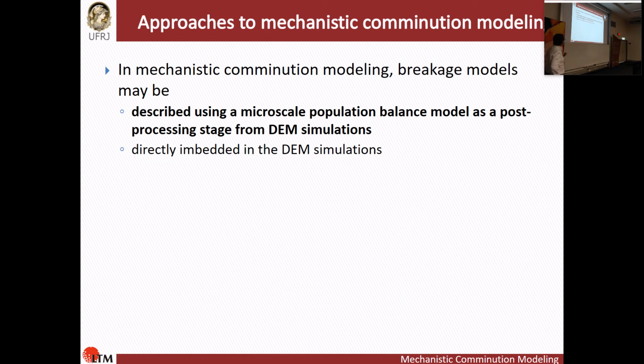There are two options. First is, can we actually do this separately from DEM? Because anyone who works with DEM knows that obviously the number of particles that you have in a simulation is going to impact quite a lot the computational effort. So the first option here is, can we get away with just simulating the grinding media in the mill or a system and just do the breakage prediction as a post-processing tool? And the second is that no, in some equipment you cannot do that. You have to have the particles breaking, otherwise it won't be realistic. A crusher is a very obvious case of that. So we'll tackle these two problems during the rest of my presentation here.